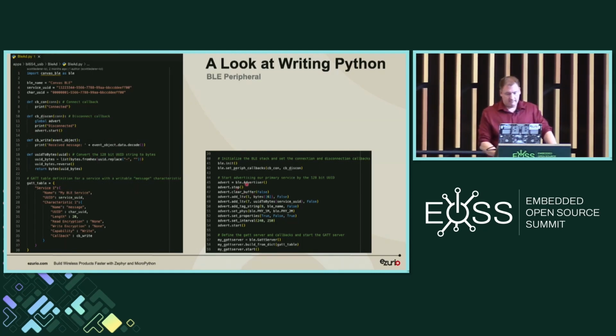And then we have a function to set up the advertiser, right? Peripheral advertises. So we get access to that new object, stop it, kind of clear everything out. And then we have some nice APIs for adding to an advertisement. Advertisements work by length tag values. So in the BLE spec, there are certain tags that are for different fields in an advertisement. So right now they're just defined as numbers here, so it's not too friendly, but you can look in the BLE spec for what 1 and 7 are.